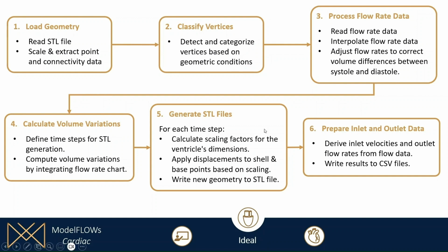And here, another important thing is to define the time steps we want to create, because it will be the same time steps for our STL generation. And finally, we will generate our STL files, which, for each time step, we're going to calculate the scaling factors for each ventricle dimension, then apply the displacements both for the shell and for all the moving points in the shell and also in the base plane, and write the STL files.